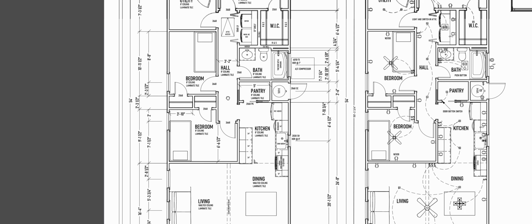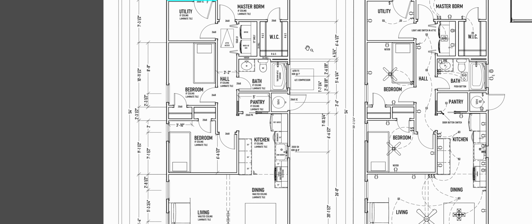So I'm going to look for walls in here that I might be able to put some let-in braces in and kind of cut this house up into some better numbers. So that's a good wall for a let-in brace. That's a clear wall for a let-in brace, but I got a toilet. Well, the toilet plumbing is not going to be super problematic. I got a sink, so there's going to be some plumbing in the wall. So as long as my let-in brace is up high, it's probably not going to matter. But I do need to think about that a little bit. And that's a clear wall right there. So I'll tell you what I'm going to do: we're going to use this wall, and we're going to use this wall.